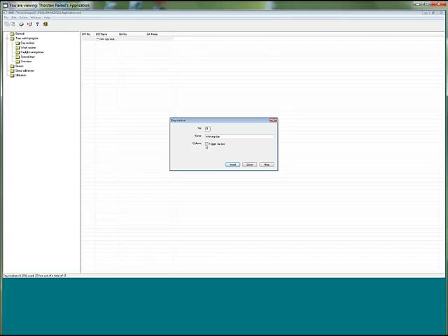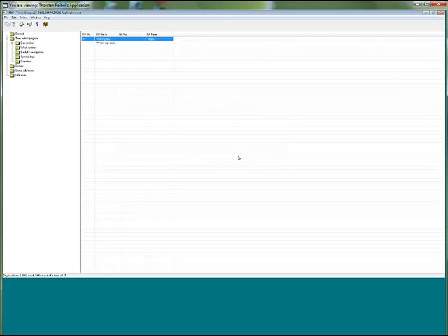Yeah. You see also here the option trigger via bus. You can add a group address here to activate and deactivate this working day time program additionally. So maybe you would like to switch off the Monday program and it's not working at certain times. Also possible. But let's create first of all a simple day routine, insert, finished.